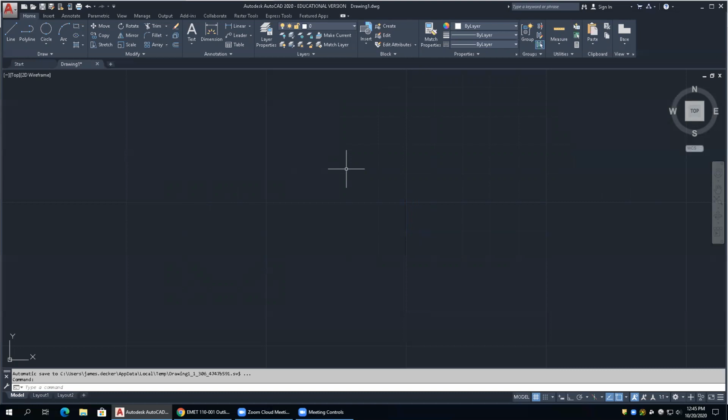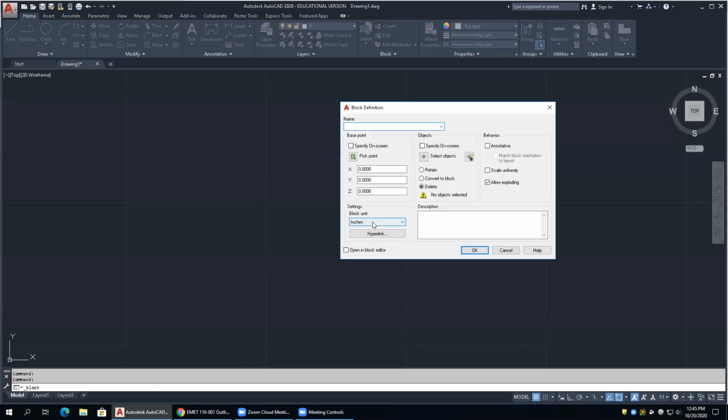All right, so now then, if we go back into the block command, but notice now when you open this up, you will see there is a block in there called logo. See that? Logo. So that now exists. Okay? Once you create a block, it's like a layer. It only exists in that drawing. Okay, it only exists in that drawing.